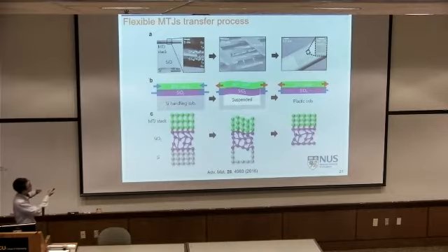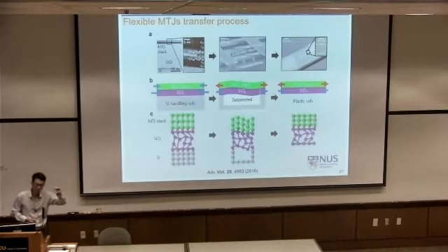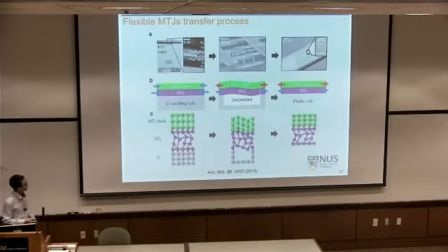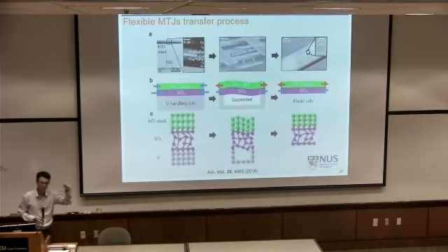Then recently, we discovered this MgO requires only 1 nanometer, a very flat layer. So it's not easy to deposit directly on a very rough surface. So we just deposit on a conventional silicon wafer, then we can etch out the handling wafer. Then those MTJs will be very thin, suspended layers. Then using a stamping technique, using PDMS, this is just your typical rubber eraser, you can just attach and then move to any foreign substrate, like this plastic substrate.